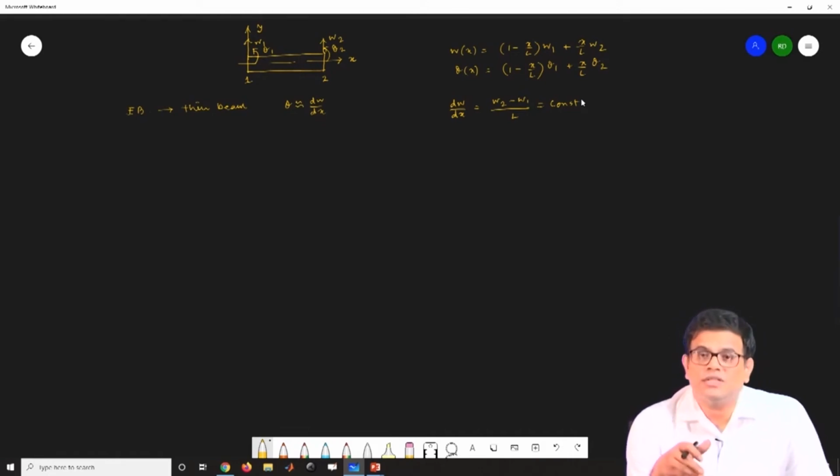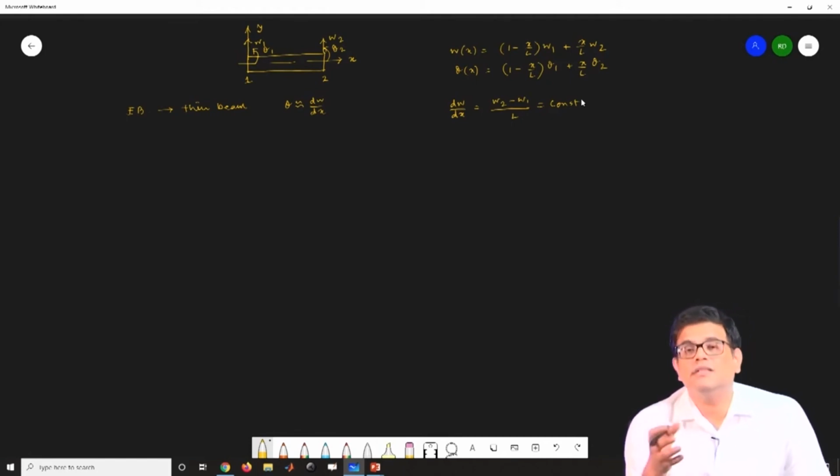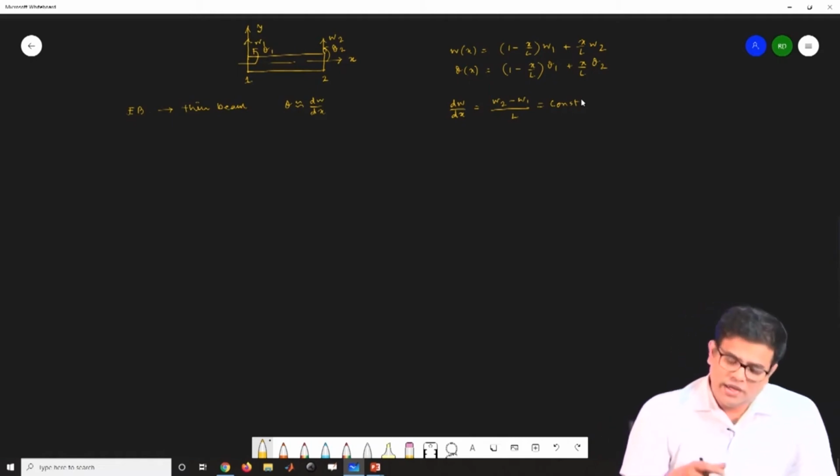So, this is an inconsistency which will actually create the bending energy to be 0 and the shear energy will be high, and for this reason the discretization or the solution will start giving garbage values as the aspect ratio, or the thickness to length ratio, is growing in terms of increasing aspect ratios.